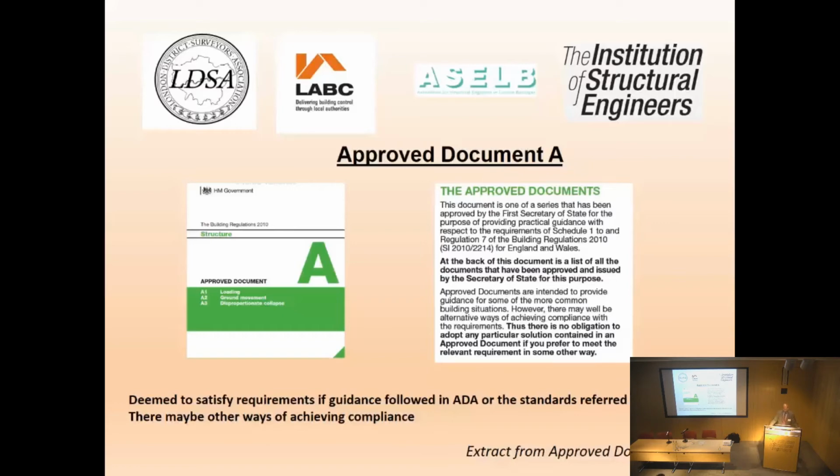You'll find quite a number of documents referred to in the back of Approved Document A. It's always important to remember, as structural engineers and other construction professionals, that the approved documents are not a prescriptive document. A number of years ago, to try and prevent stifling of design and to allow freedom of design, it was made very clear in not just Approved Document A, but many of the other documents, that we shouldn't be prescriptive. If you look at some of the older documents, they do tend to be very prescriptive. This is to allow freedom of designers.